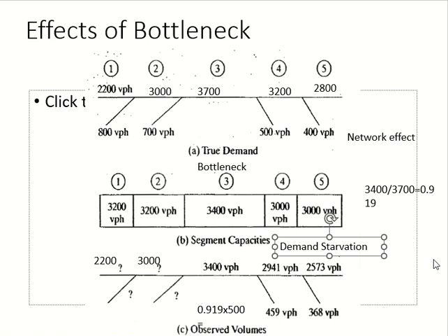Now we have a problem in segment 3, right? I should increase the capacity of segment 3. Okay, let's say I add a lane in segment 3. Now the capacity is more than 4,000. Capacity in segment 3 is more than 4,000. Okay, so for segment 3 no problem, right?